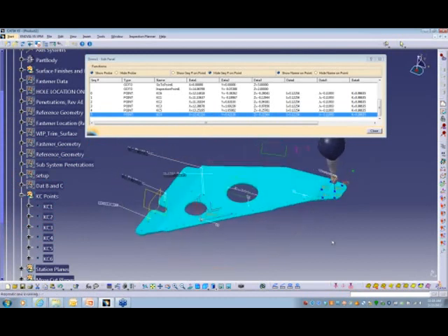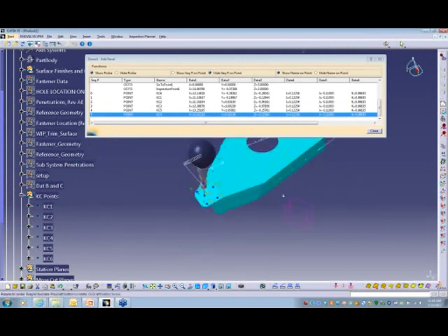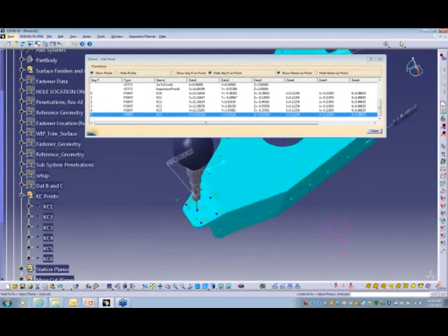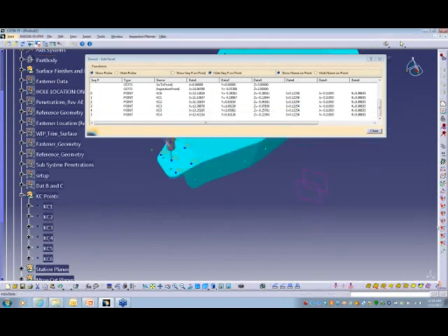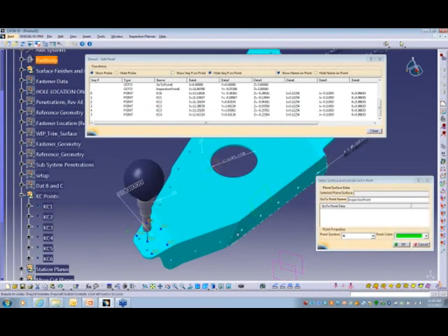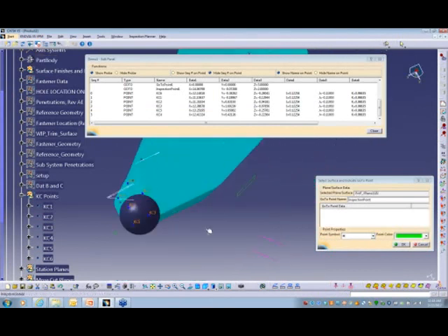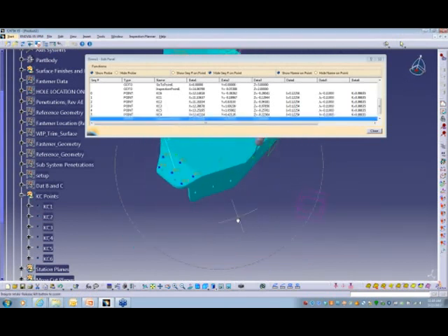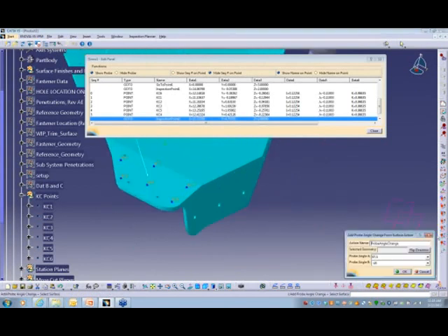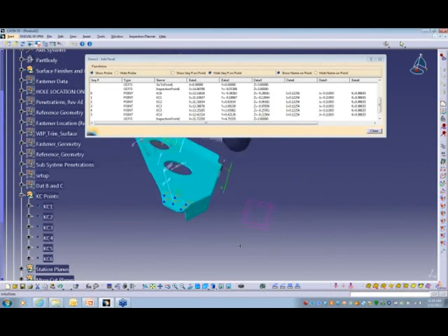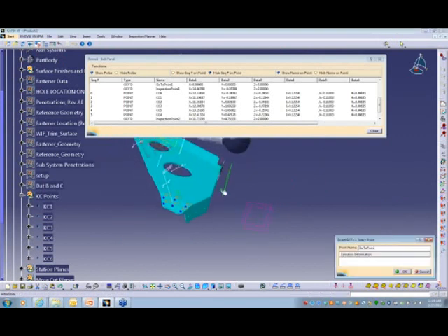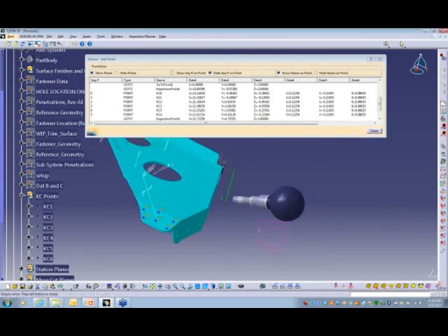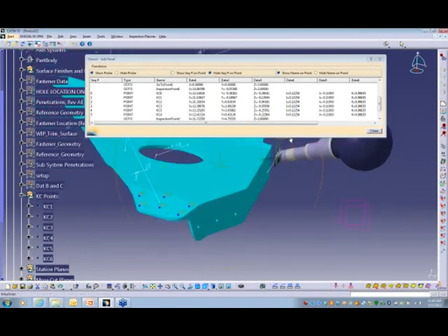We'll come over here. Let's say that we want to measure this contour right here. We'll do another go-to point on this plane, bring the probe over to here. Let's say that we want to align the probe to that surface. We can hit this button here, pick that surface, and it's telling us what the angle should be on that. We can change the probe angle, so we just align the probe to that. I always believe in going back to where it came from when you do a probe change, so now we're aligned to that surface.